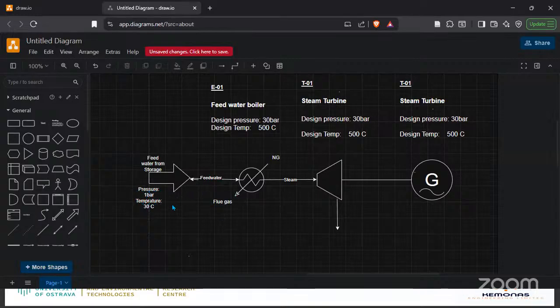Already we have a heater that will raise this to 300 degrees Celsius, right? So this was what we skipped. So we need what? A pump, right? Do you all agree? To increase the pressure of this from 1 bar to 30 bar, you need a pump. And the reason we need that is because we need to move this fluid from one point to the other.